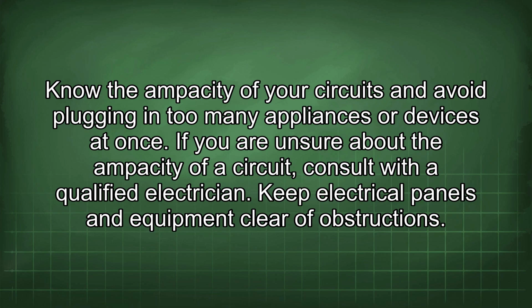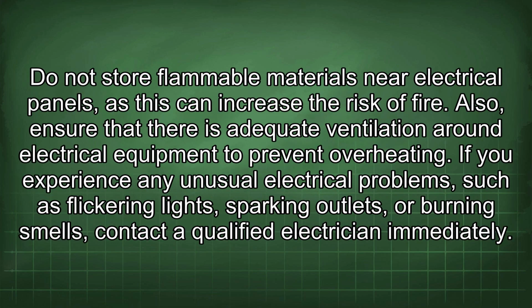Keep electrical panels and equipment clear of obstructions. Do not store flammable materials near electrical panels, as this can increase the risk of fire. Also, ensure that there is adequate ventilation around electrical equipment to prevent overheating.